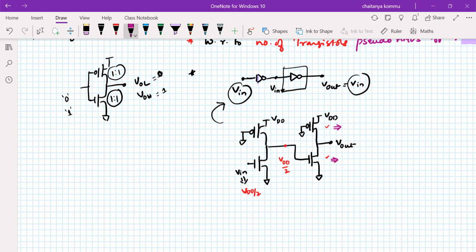As soon as the NMOS gate voltage is more than the threshold voltage of the NMOS transistor, it will enter the saturation region, as we have studied extensively. Then the PMOS transistor will be in the resistive or linear region. These are the two important points we should know.